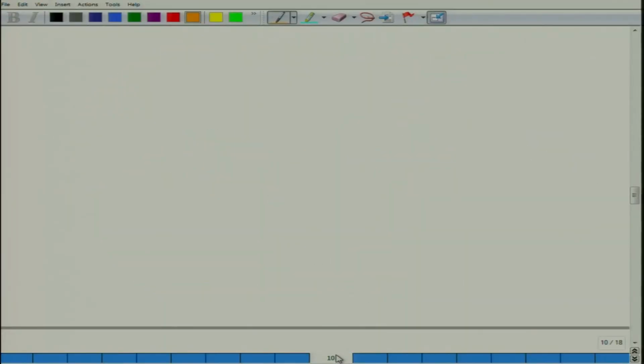So we have so far talked about the short dipole or elementary dipole. We have seen that the elementary dipole does not really have a large directivity, and it is also not a completely practical example, because you do not want to fabricate just a small nail or a small bead, and you have to be careful that this delta L is much smaller than the wavelength you are considering.